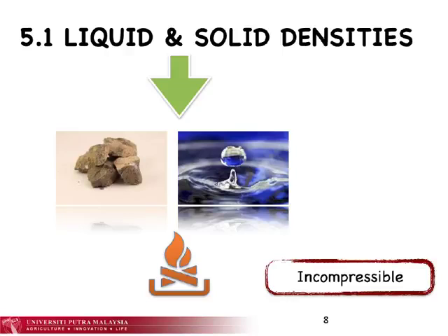When you heat a liquid or a solid, it normally expands, which means its density decreases. In most process applications, however, it can be assumed with little error that solid and liquid densities are independent of temperature. Similarly, changes in pressure do not cause significant changes in liquid or solid densities. These substances are therefore termed incompressible.